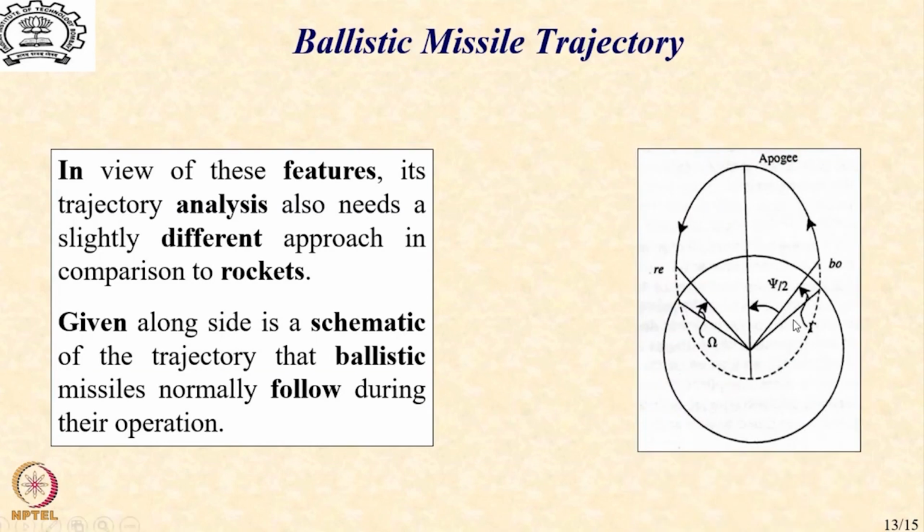So in this, we assume that there is an altitude point represented by burnout, BO, where the missile is given a velocity with which it starts traveling in the gravitational field of Earth, and from our projectile motion understanding, we know that in the absence of drag, it will reach a highest point above the surface of the Earth, which is commonly termed apogee or maximum altitude point, and then the altitude will start decreasing and it will start turning back towards Earth until it will reach a point which we call the re-entry, which means it will re-enter the Earth atmosphere,